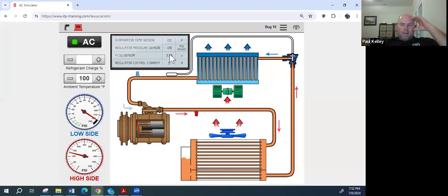Make sense? So this one, you really needed the tech stream. The tech stream is what fixed this vehicle. Knowing how that sensor works and looking at it. If you don't know how it works, read about it. If you can't find the information you need, hopefully you can compare it to a known good, like we did in this example. All right, so that gets you through all of them.